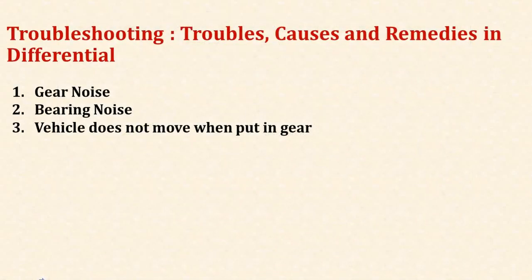Now let's discuss some of the points of troubleshooting. We'll focus on the troubles, their causes and remedies in the differential. So the first trouble we consider here is gear noise. Generally, the cause is insufficient lubricating oil, and the remedy is to replenish with the correct amount.